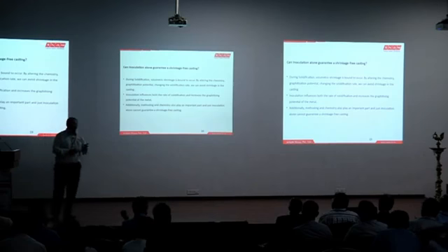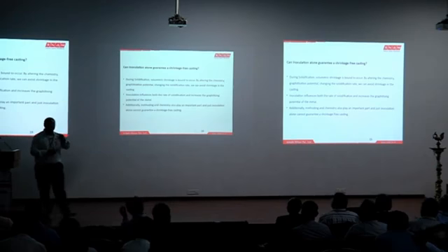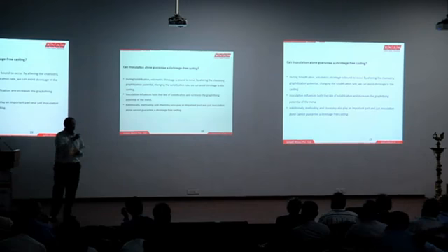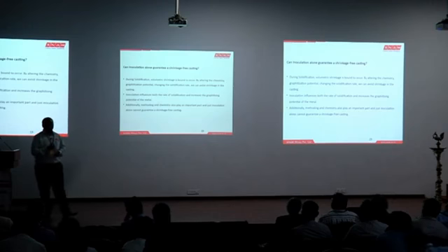inoculation supports. What inoculation does is, say for example, a ductile iron with 3.5 carbon, 2.4 silicon will be giving you, say for example, X amount of nuclei. Sometimes this X can become X minus delta X or X minus delta X1. This delta X1 is given by the inoculant. Even if you do not add the inoculation, you will still be getting X minus delta X. But this delta X keeps varying heat to heat, and you might not be able to attribute it to any of your foundry parameters directly. So to avoid this variation, inoculation helps.